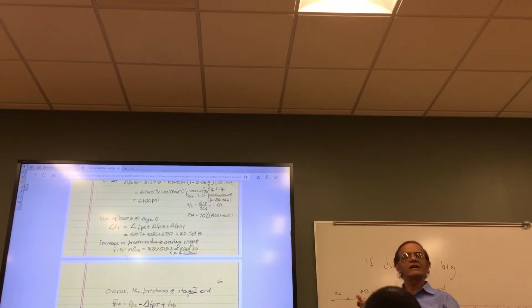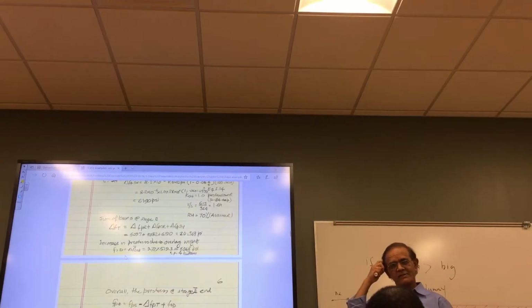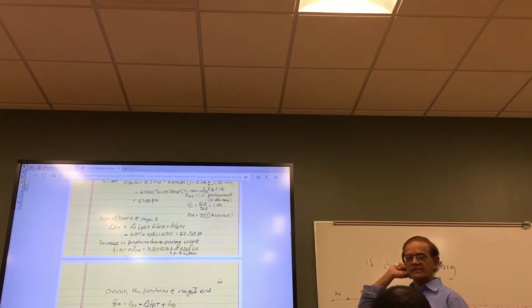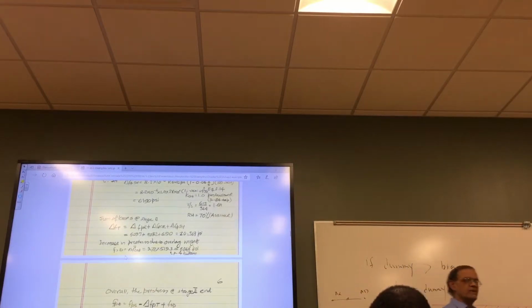Beyond that, your beam is going to behave like reinforced concrete. Once you start cracking, it's no more under compression. That's the beginning of your end, not end really, but your reserve capacity is now coming into play. Your normal elastic behavior is lost.